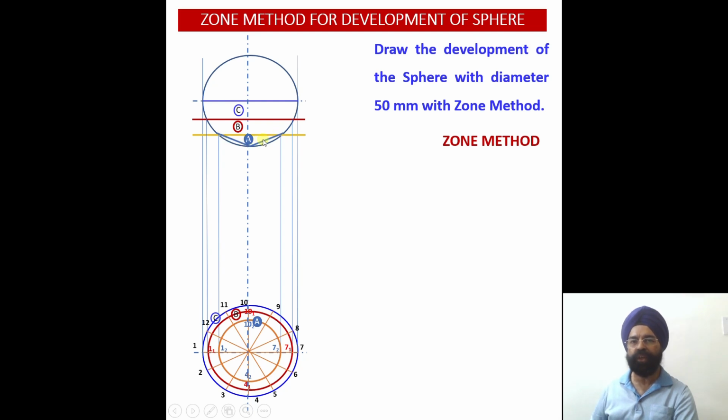Here these are the two slant edges. We already know by now how to make the development of a cone. For the development of a cone, two things are required. Number 1, the true length of the slant edge. I have that, this is my true length of the slant edge. Using this with O as the apex point, I am going to draw a circle over here like this. Please check, I have drawn a circle using O as the center, the apex point, and then I need to make all these segments over there, because all these segments correspond to the innermost circle.